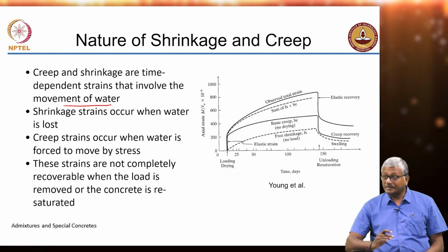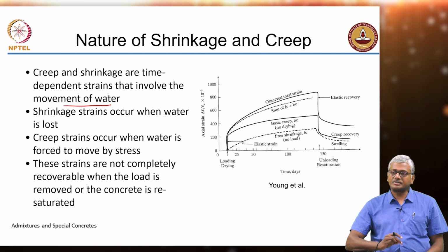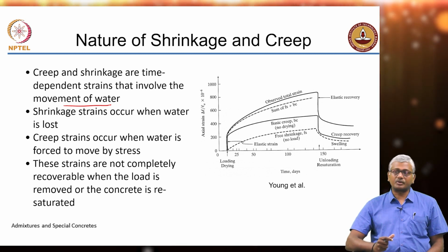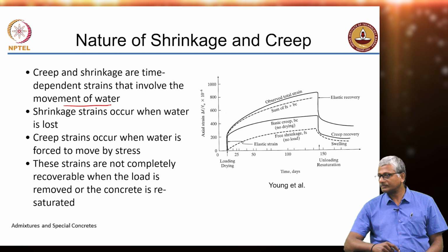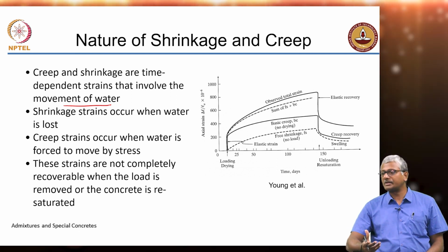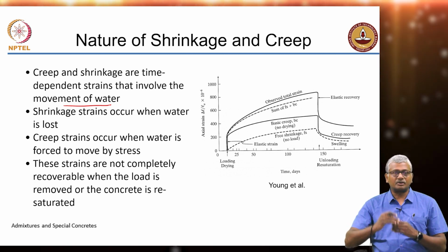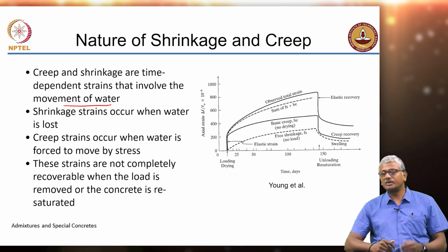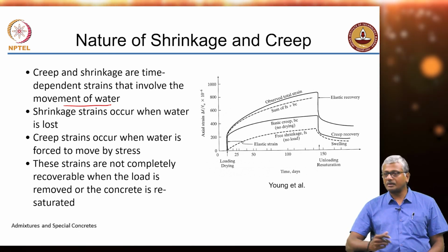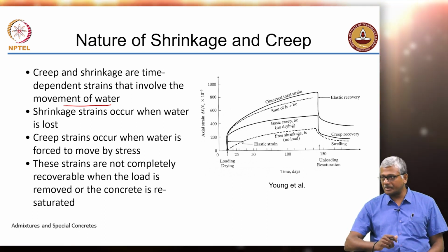Because of this, design for creep becomes quite significant in structures that are expected to be dimensionally stable. For instance, if you have columns in tall buildings, right. If you have columns in tall buildings, ground story columns are typically expected to be high strength concrete. Now, if there is any change in height of the column over time, that is going to affect the way that the load is distributed across the rest of the building. So, it is very critical to define this extent of creep and have some means of actually measuring it properly.